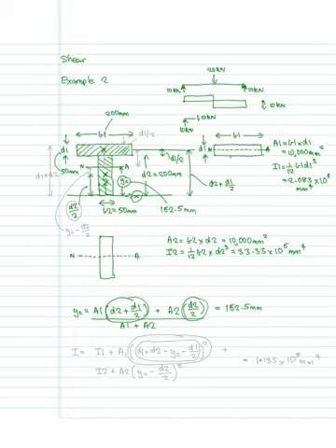In our stress distribution we've worked that out to be 162 millimeters from the bottom face, and if you'd calculated YC relative to the top face, you would also get the same position. Okay, now having calculated the centroid as being 162.5 millimeters, we now need to calculate the second moment of inertia.